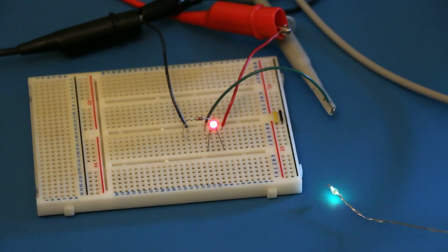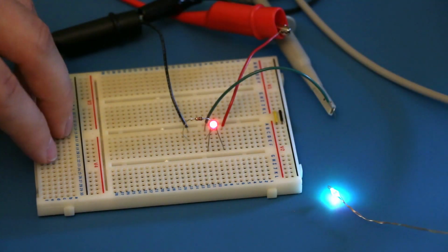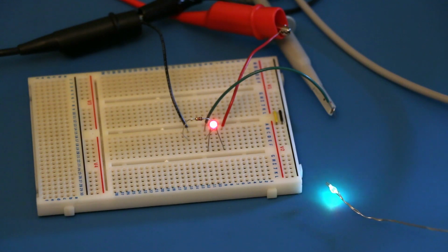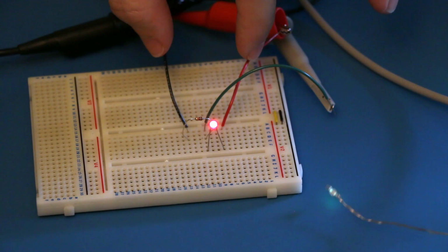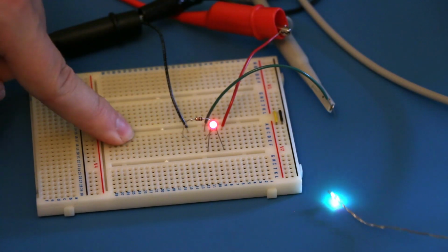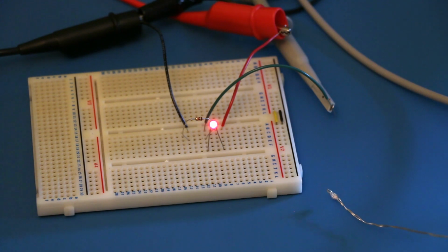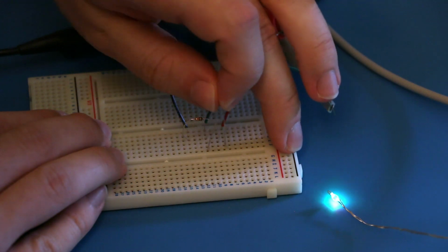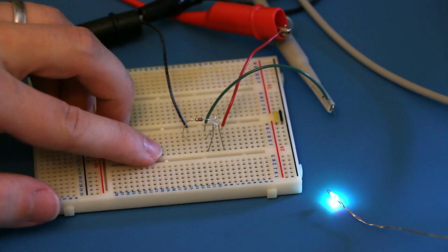Just a quick look at the breadboard and the circuit I'm using to catch the light output from the chain and trigger the oscilloscope. I found a nice clear red LED in my bag of miscellaneous LEDs, and it's currently wired up across a 3.3 volt power supply with a 1 kilo ohm resistor. Now, to make this LED work as a light sensor rather than a light emitter, we have to reverse bias it. That's simple enough, and of course it prevents the LED from lighting up.